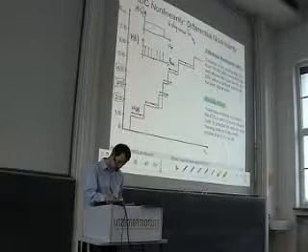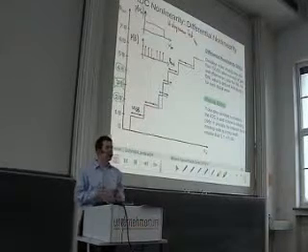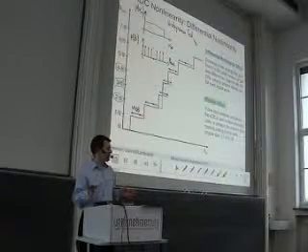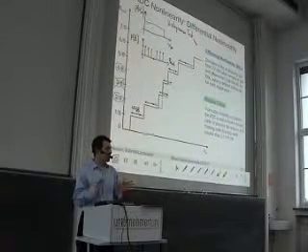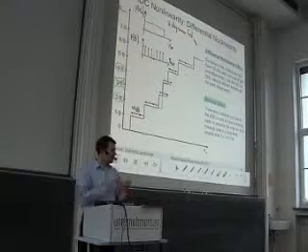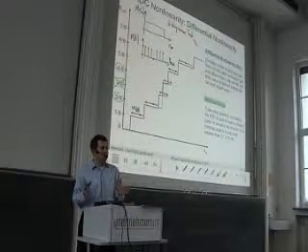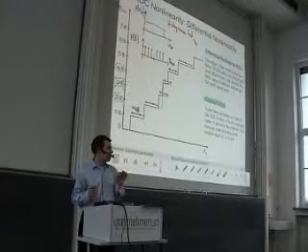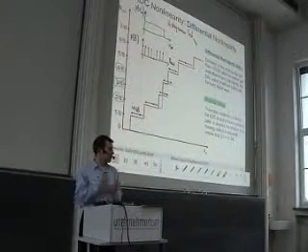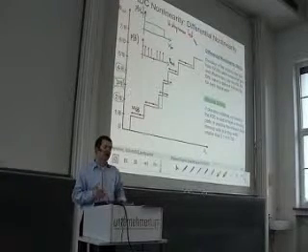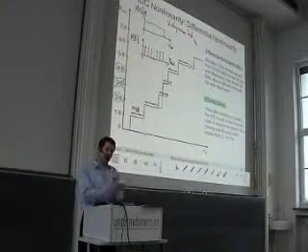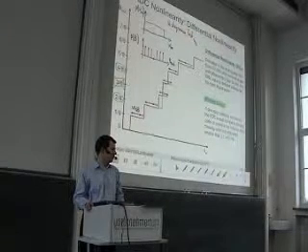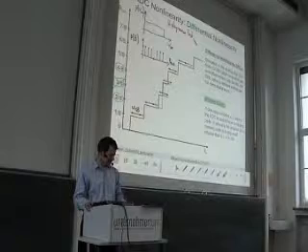And the histogram test is something that reveals nonlinearity in measurement without measuring a complete characteristics. Because for a perfect linear converter, having an equally distributed input signal should result in an equally distributed output signal. And if the probability of one signal is much larger or much smaller, then this is an indication that the step width here is much larger or smaller. So this is an indication for nonlinearity. Okay.